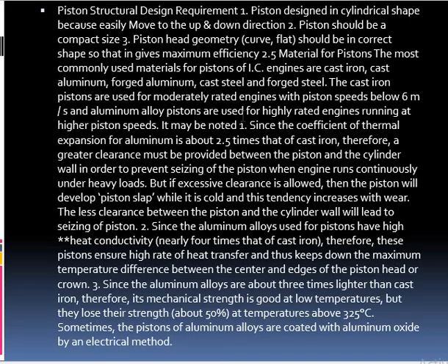But clearance should be allowed. Otherwise the piston will develop piston slap, which has a tendency to increase wear. Whenever the piston structural design is not proper, or to prevent seizing of the piston when the engine runs continuously under heavy loads, clearance should be allowed, or the piston will develop slap and the wear will increase.